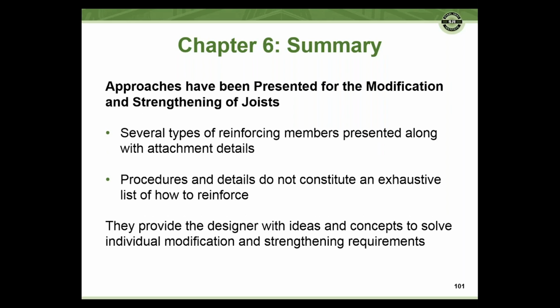So in summary, we presented some approaches for modifying and strengthening joists. There are several types of reinforcing members, several ways of reinforcing members along with the attachments and their details. Procedures, we've given you some procedures and details to do this, but remember they do not show every possible way you could reinforce. There are several other things you can do to reinforce members.